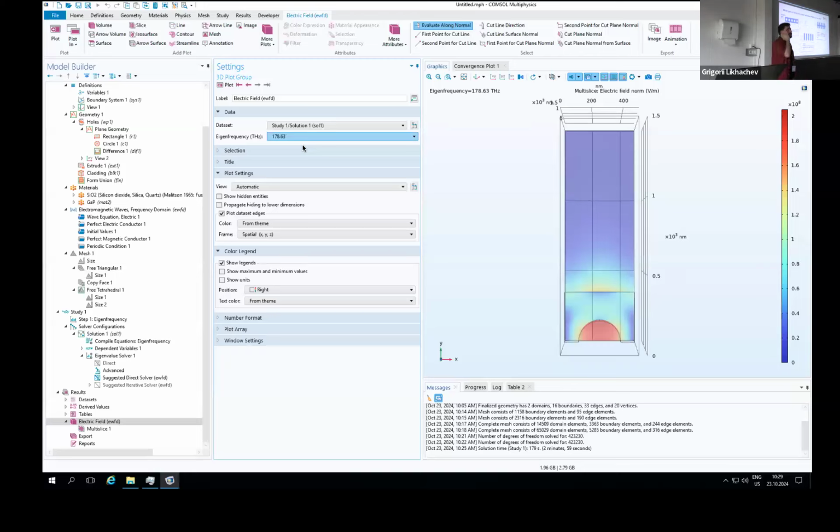So in the end, what I'm going to show you now are my results for this structure. They have a very large bandgap. The sidewalls are fine, and the maximum of the electric field is in the middle of the holes. On these two sides, above and below the holes, you don't see any roughness. You only see it here close to the holes. So I think it's a good trade-off. Of course, the holes are small, and you need to be able to fabricate them. It's not easy. It's much easier to do the other two.